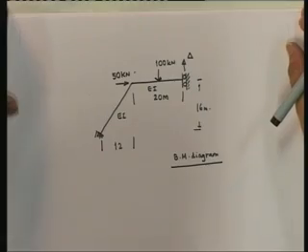Now, from this point onwards, I'm going to stop using theta B, theta C, delta the way I've been using till now. I'm going to start defining the structure degrees of freedom using a notation R. So in other words, suppose I have 3 degrees of freedom in a structure. I'm going to call them R1, R2, R3. Now R1 may be a rotation, R2 may be a displacement, all that does not matter to me. I'm going to define them as corresponding displacements. If the displacement happens to be a rotation, rotation is also a general displacement. Just like when we say force, I mean not only a linear force, I also mean a moment. Okay, so this is the problem.